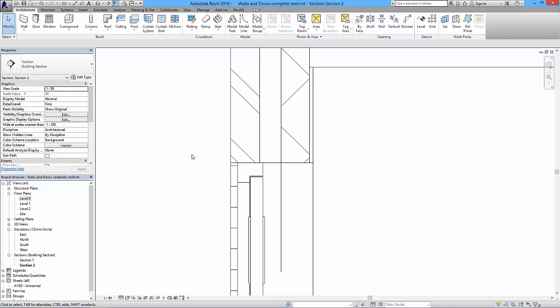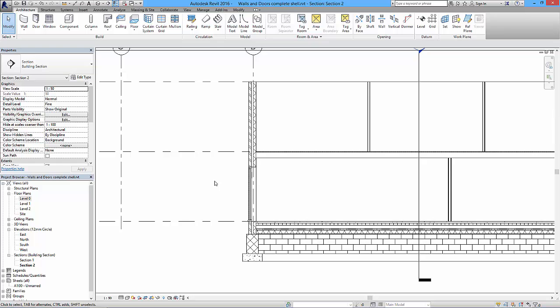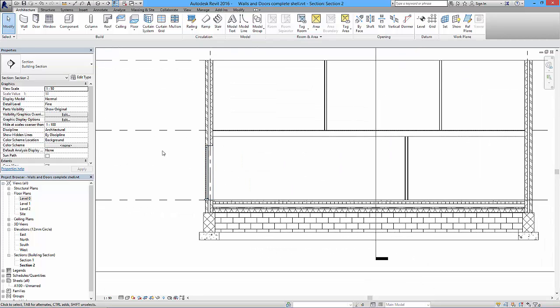As far as Revit is concerned, stuff at this sort of level, 1 to 50, 1 to 100, is all kind of indicative, and what you do get is the count of the door, the number of the doors, the type of the door, the position of the door, so in plan, elevation and section. And what that does mean is that you get full appreciation of the door and its location to other objects within the project. And what it doesn't do, and that's quite rightly in my opinion, is deal with the detail at this sort of scale. You wouldn't really want to model all the bits and pieces that go in that.